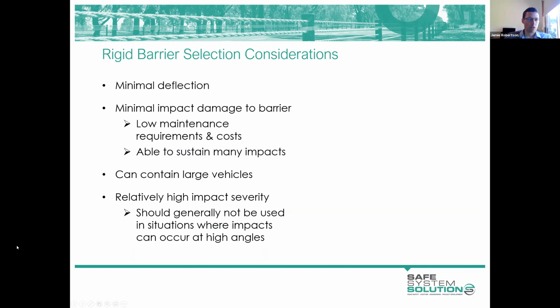Low maintenance, they perform again and again without any intervention. Typically, they have a higher containment level than more flexible systems. But the downside, as I say, is the impact severity. So because of that, we need to be mindful of where and when we install rigid barriers.